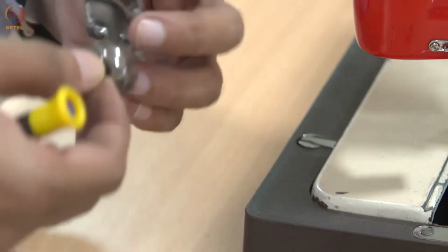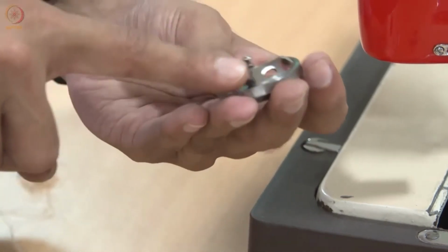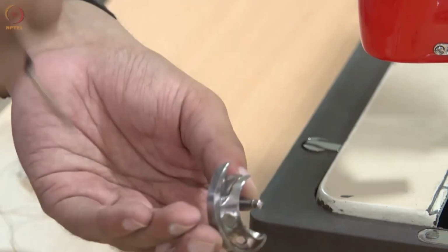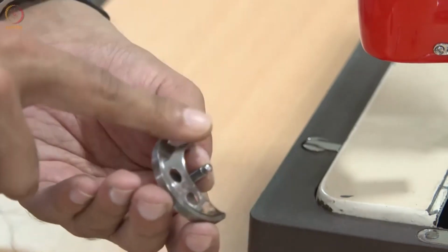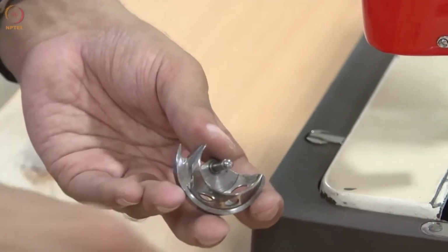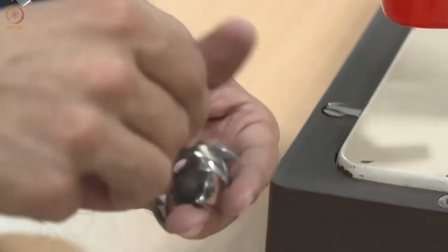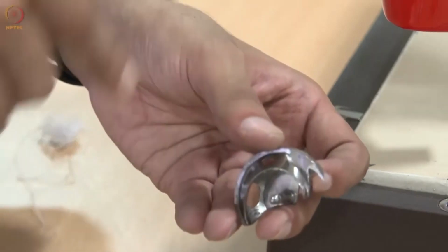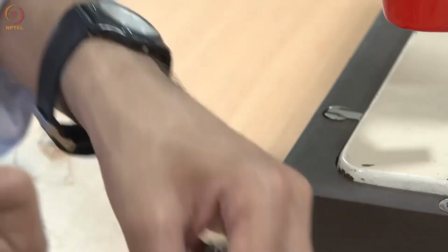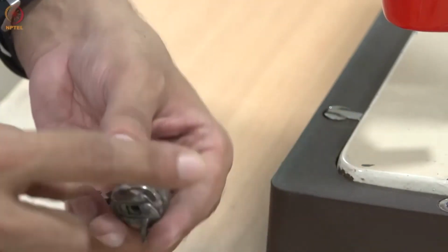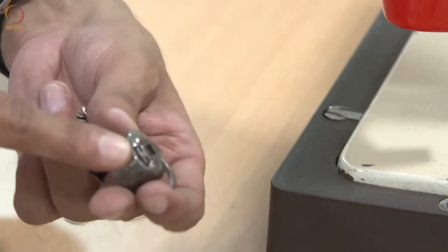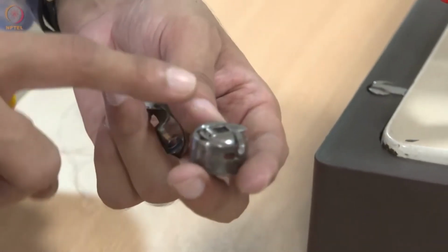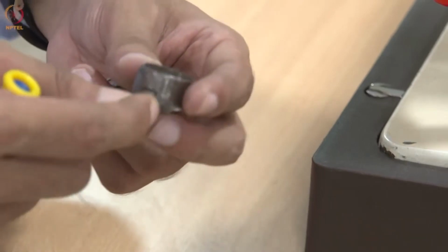So this is a way you can hold the spool in place. And if you observe carefully, all the surfaces here are polished to a mirror finish. The surface roughness is very, very low. The reason is, all these surfaces come in contact with thread. If there are any rough surfaces like we saw in the casting before, that will catch the thread and break it. You can see all the surfaces, even though this is rusted, if you look at a new machine you will have what is called a mirror finish.